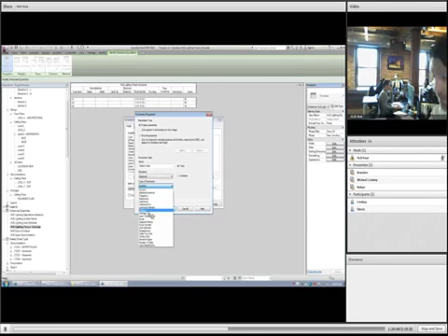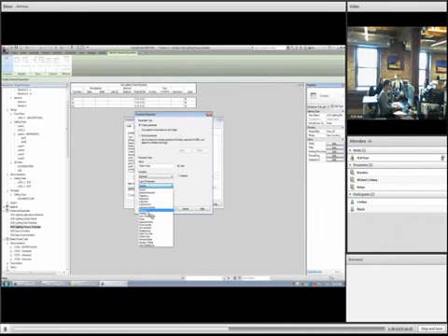Units are very important to Revit. That's one problem with parameters here: if you try to do more parameter customization, Revit's not good about converting units. So if you're trying to do LPD, it's very hard. You have to make sure you have the right units. I have one set up already for you that's calculating this. But to try to get watts per square foot and get wattages summed, you have to just make sure all of the parameters are utilizing the same units. It's not good at converting.